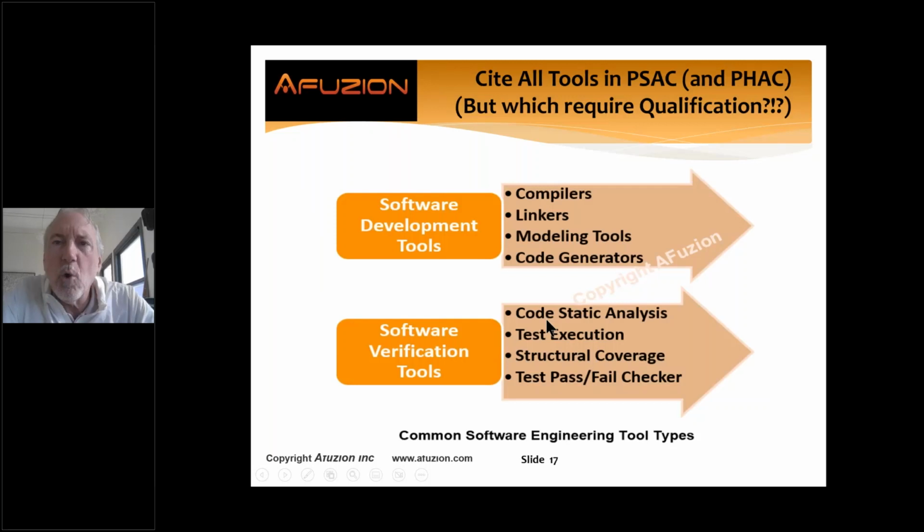Now, tool qualification. Big problem in PSAC and big key area. All of these are tools. Tools, remember, are software that doesn't fly. Tools are software. They're programs, but they don't fly, so 178 does not apply to them. Instead, DO-330 applies to software tools. These are all software tools.